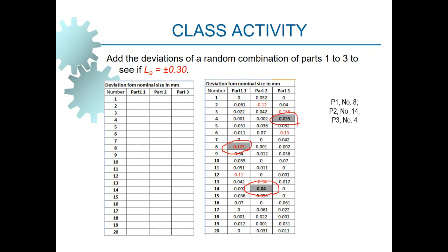And as you can see, the one in the first pallet, which is part number 8, is in red. The ones that are in red are those parts that exceed the specified tolerance of plus and minus 0.1. So we should have scrapped these parts if we wanted to make use of the traditional method of tolerancing. However, we have not.